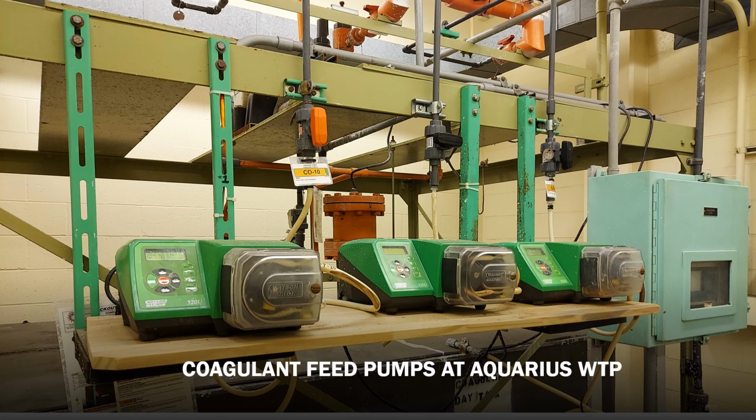This is a picture of the 3 coagulant pumps at the Aquarius water treatment plant. Remember, each one of these pumps has to be able to handle all the load at any given time. The other 2 would be in standby, and of course they rotate these pumps from month to month to month to be sure that they're always working in good order.